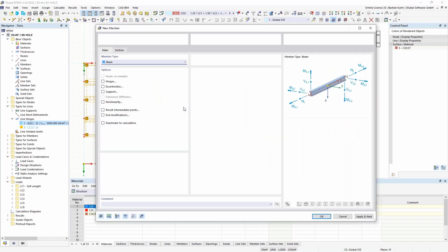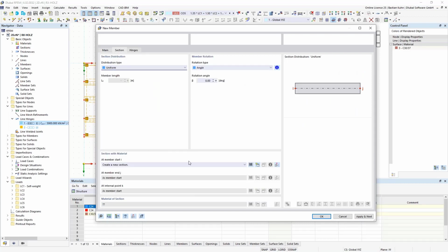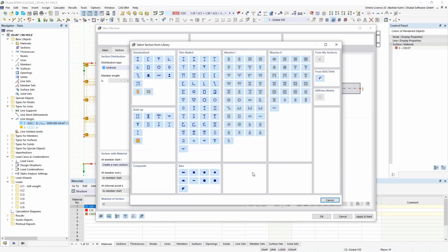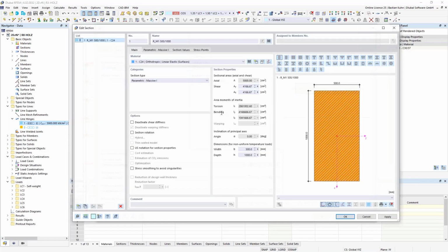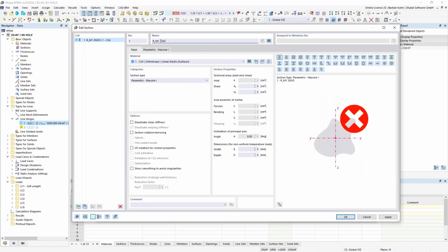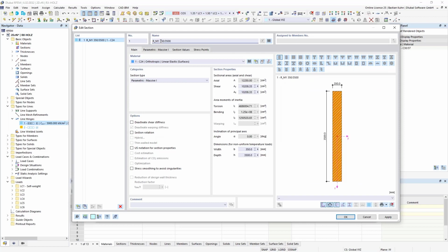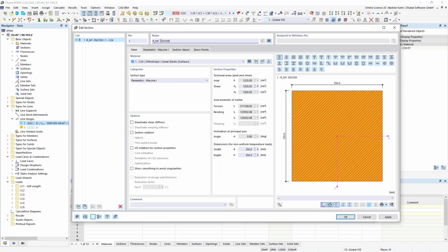The first floor of the structure is made from concrete, but all the others are made from timber. That's why we choose as a template now the timber section in here. We choose a massive section with a value of 35 by 30, oops, not 3 meter 50, but 35 centimeters.